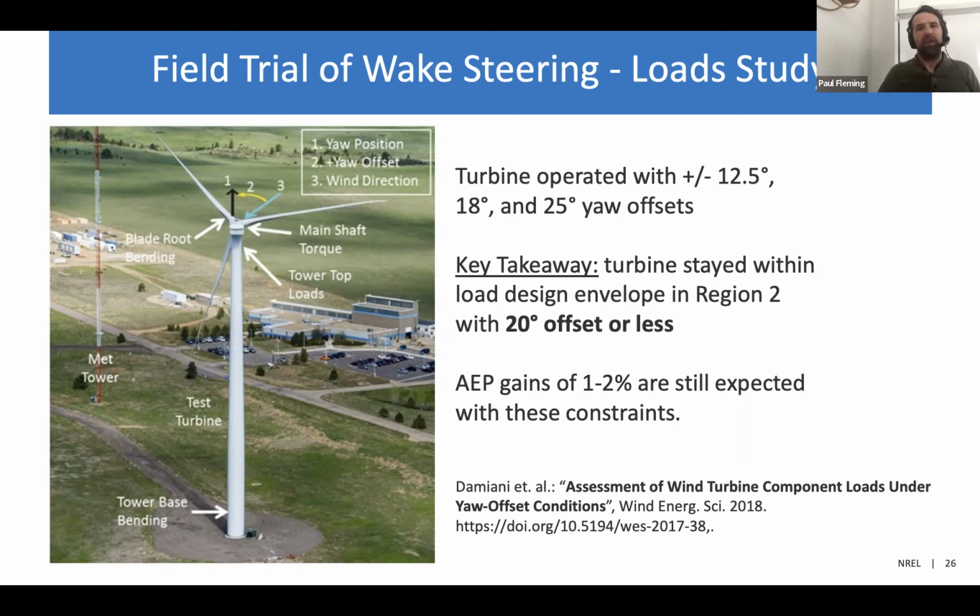So this slide is just one of the reasons for the loads impact. I think when people first hear of the concept of wake steering, there's an assumption that the loads impact should be pretty large. One of the things to stress is that wake steering is only done for certain wind directions, but also only for certain wind speeds. For a lot of the higher wind speeds, where some of the bigger loads will be, you don't actually do wake steering because there would be no point.